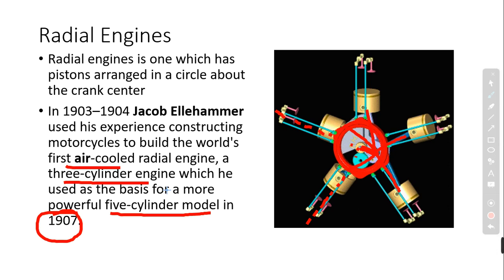What the advantage is that the speed range for the radial engine is higher than the multi-cylinder inline engine. So these can be used without a power transmission system. That is very useful to reduce the weight in the case of aeroplanes. That's why it is most commonly used in aeroplanes and not commonly used in four-wheelers. Okay, now that's all for the introduction.